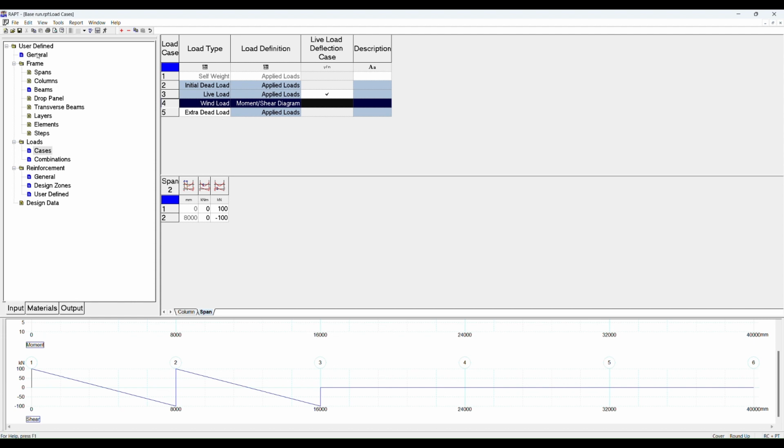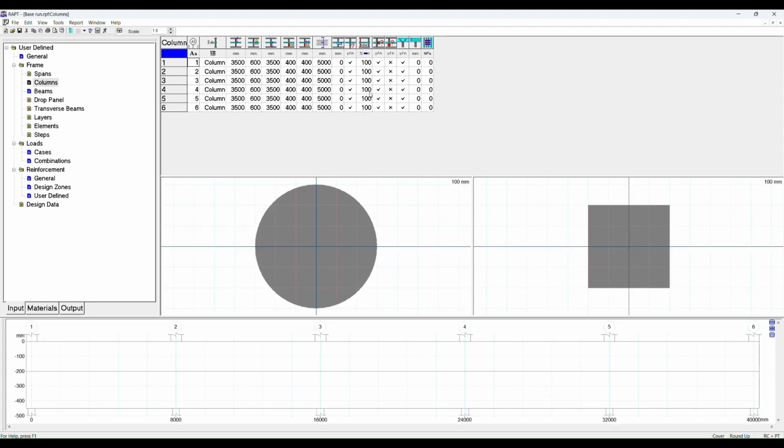If you go to columns, you can select whether or not the columns have a restraint. If you unclick the restraint, essentially you're saying it's a sway frame. Because you don't have an actual lateral load applied to the frame, there is no sway frame analysis. But the reason I raise this is that if you have those restraints switched off so that it is essentially a sway frame, RAPT will not allow any moment redistribution. So as soon as these are all crossed, there is no moment redistribution. If you say they are braced by some stiff core or something else, then RAPT will redistribute moments.